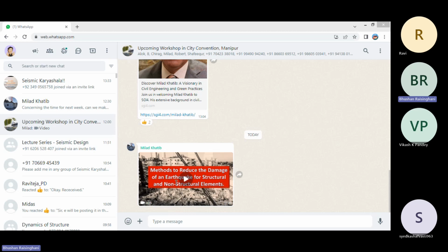In which the column detailing has been mentioned, and it will also have the same PMM interaction curve as that of a column. So it will behave as a column and be designed as a column, and in between the boundary elements the wall will act as the rectangular web of the shear wall. Based on that you have to provide the nominal steel or what is required for the generated forces. Based on that we provide the reinforcement that way.